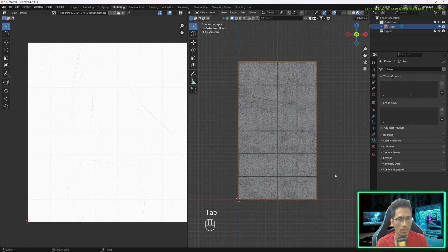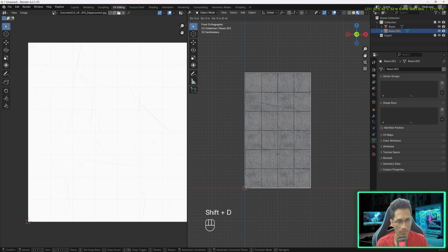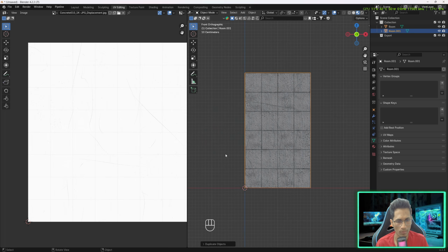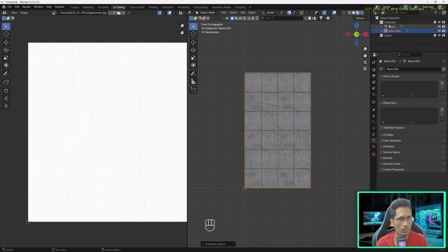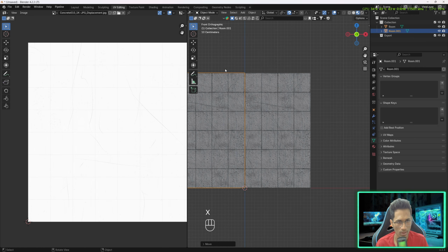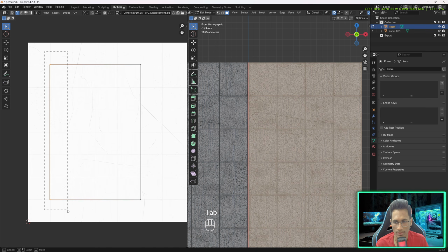All right, good. Now if you duplicate this wall by Shift D, press X to move it in X direction and press right click. First enable this magnet, make sure increment is set to true. You can see there is another room duplicate, GX, and just touch it. Okay, so you can see it is visible. So I'll select this again and just barely touching.